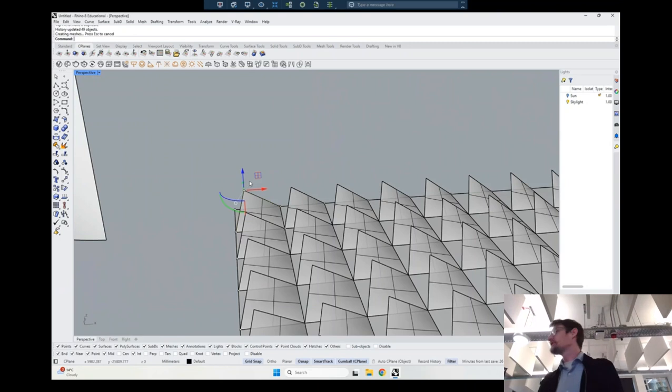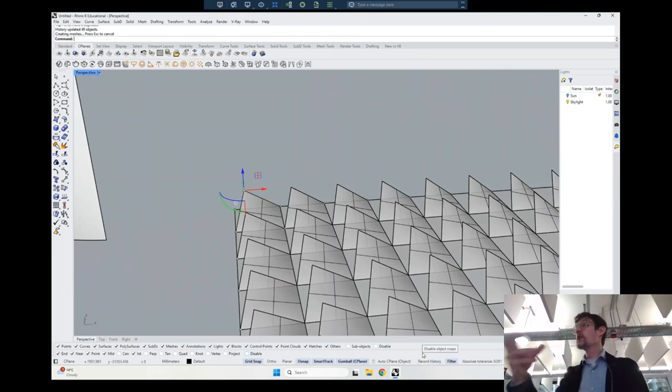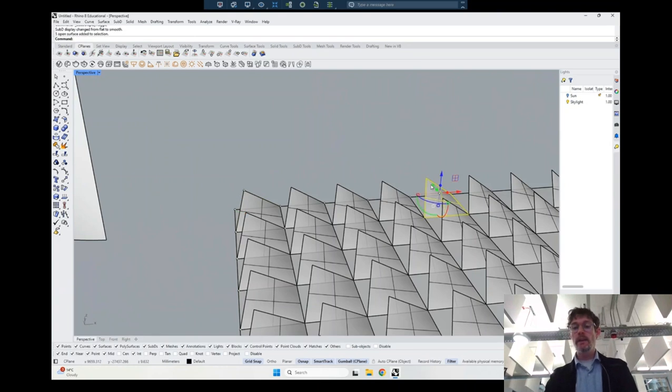If you're used to things like Blender or 3ds Max, it's kind of like that. What I did effectively is that I selected the object, I made sure record history was turned on, and now Rhino knows that there's a relationship between this object and the arrayed copies of it. Now, what you'll probably get is if you then come over here and you nudge it, it's going to give you a warning. And the warning says dragging broke history on one object.